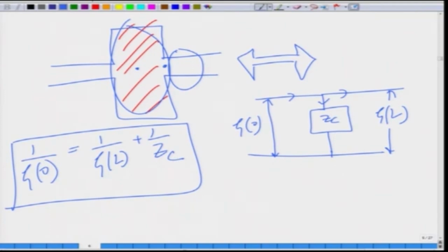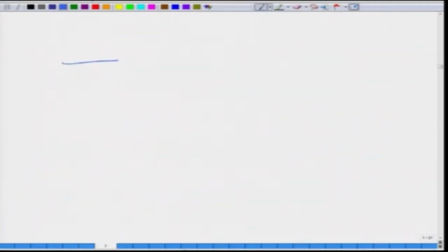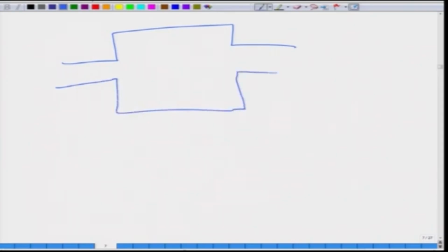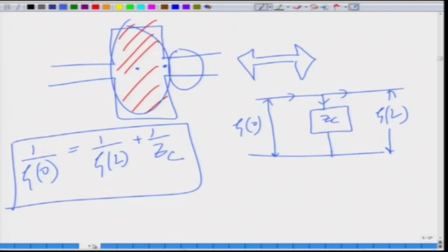That is the reason that we talked about the lumped element behavior of a tube, because eventually a muffler can be considered, and the most simple muffler is the simple expansion chamber. By studying lumped analysis of such systems, we can get to know the basic behavior of a muffler at very low frequencies.